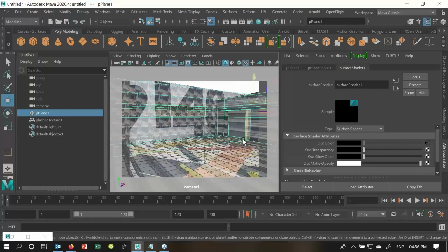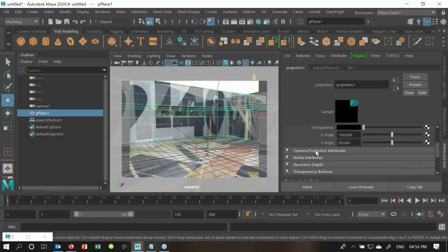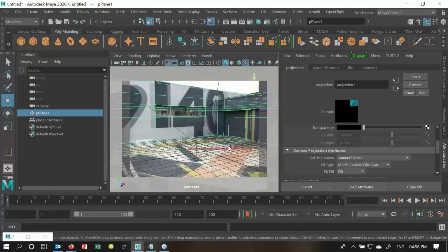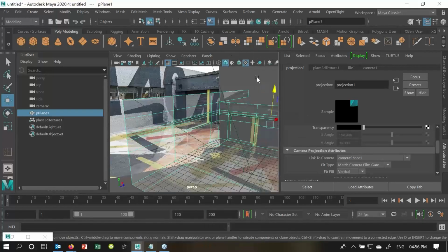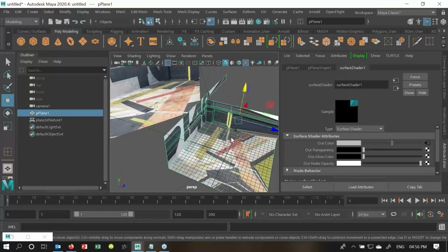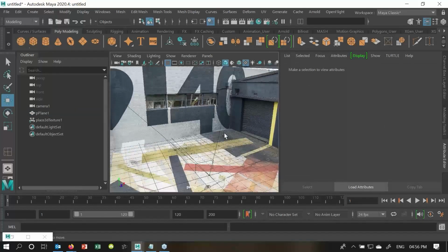Make it 5:6. Here you will see this is not coming as per our requirement. Now why is that? Because we need to use projected perspective. But which perspective? We need to select the camera because that has to be with our camera, not the fill, and the vertical type. See, my scene is created. If I go to my perspective, I'll go to the object mode and remove the X-ray mode. See this? Very simple here, we see because that was not our projected.